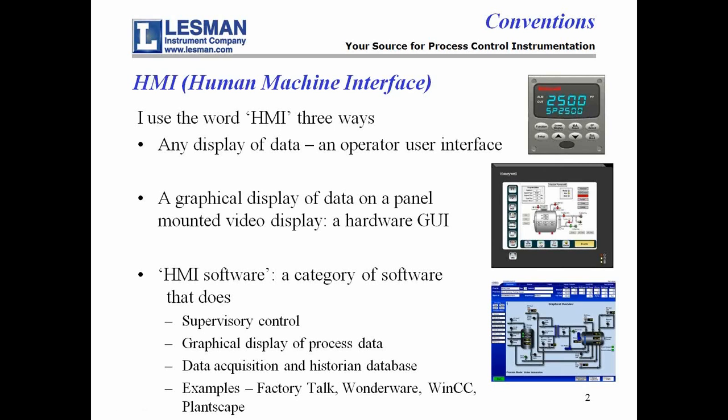Then there are the HMI panels that go in, and they're graphical panels. You can see on this one down here, there's a tank with push buttons, soft push buttons, and that kind of thing. They're everywhere out there in the control world. And then there's the category of software called HMI software that does supervisory control, has the tools for building graphic displays, does data acquisition, and builds an historian database so that data can be trended. You can read the examples down there. There must be 100 different products out there that fill the category of HMI software.